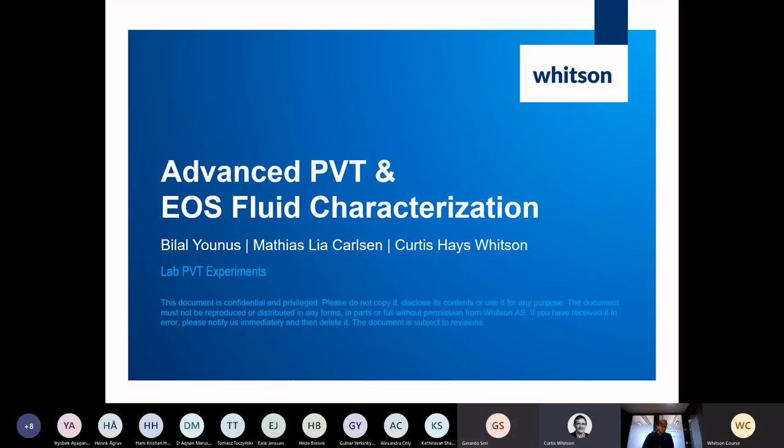You may have samples deeper and you may have samples shallower, and there can be a variation with depth away from the gas oil contact, right? So the samples away from the gas oil contact becoming more undersaturated in the oil and maybe still near saturated in the gas, those samples away from the gas oil contact won't be equilibrium samples.